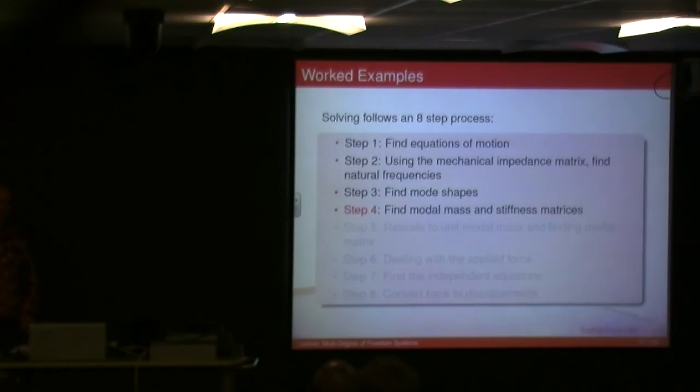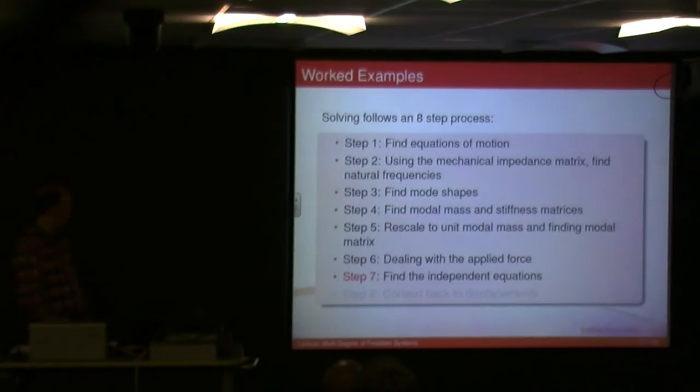Step 4, this is a new thing, is you find the modal mass and stiffness matrices, okay? Step 5 is you rescale that modal mass to get unity, okay? You then deal with the applied force. You then find the independent equations, so your q double dot plus omega squared times q equals your applied force, okay? And then you solve that equation and you convert it back to your displacement.